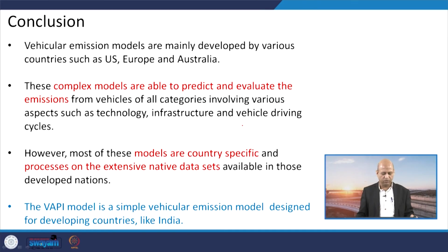So, this is all for today's introduction, on what kind of models are available and what kind of new efforts are needed. This might have given you a broad picture about emission models, basically how emission inventories are developed. These emission inventories are nothing but the values of emissions coming out of different vehicles at different locations. You can have a single value for a city, but you can also distribute the values grid-wise, 1 kilometer by 1 kilometer, 10 kilometer by 10 kilometer, or along the road. Those kinds of values are needed as input parameters for the dispersion models, basically.